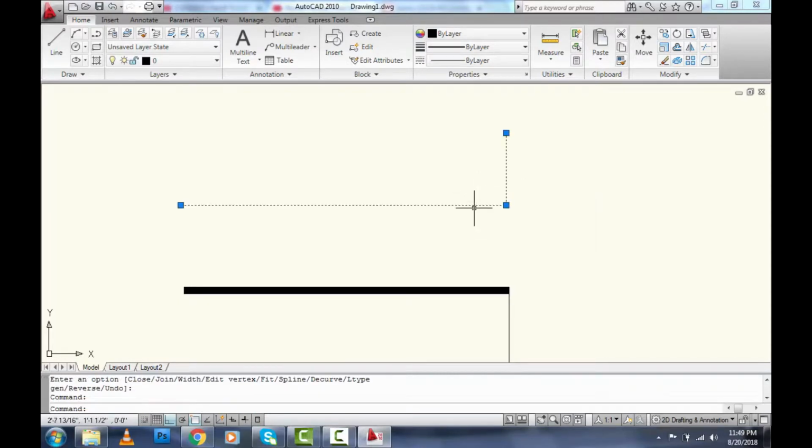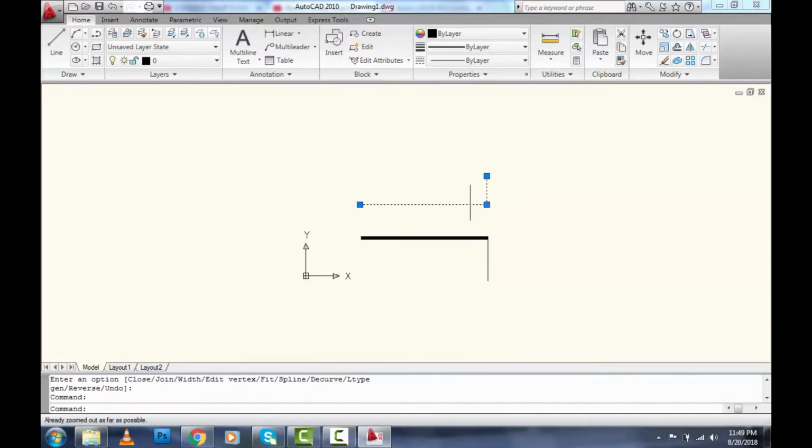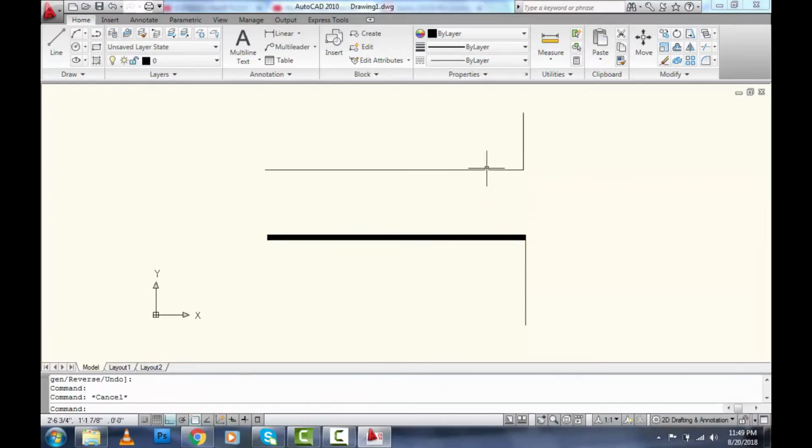Oh, it did work today. But anyways, you have to turn a line into a polyline for you to do wonders with it. So that's what we have. We have line, polyline. So this is L, this is PL, and if you want to edit this line, you go P edit. I'm going to leave a little bit of instructions in the comments below, in the video description, so that you can actually remember this.